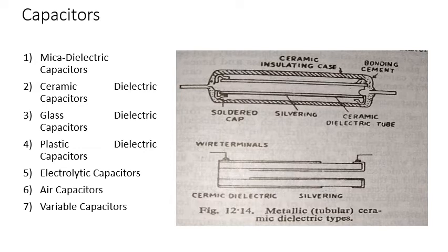The aluminum oxide film has a high relative permittivity and a high dielectric strength. For these reasons the film used can accordingly be thin, which is the main reason for the high capacitance per unit of space occupied by the capacitor. The electrolyte in contact with the aluminum anode oxide coating behaves as the other electrode of the capacitor.